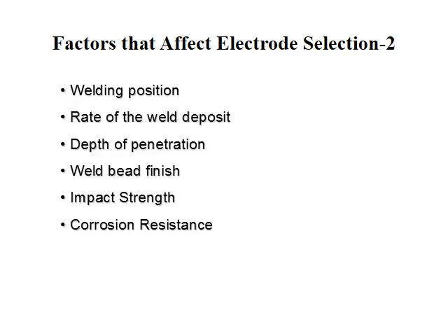The rate of weld deposit. Do we want something that's really going to have a high deposition rate? What are we looking for? Once again, the position is going to dictate the rate of the weld deposit. You're going to be able to put weld metal in faster in the flat position than you will in the overhead or the uphill or downhill position.